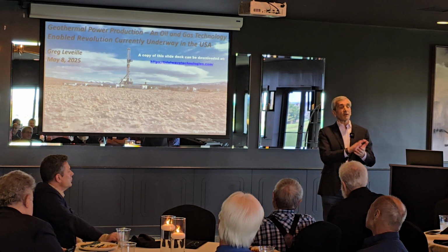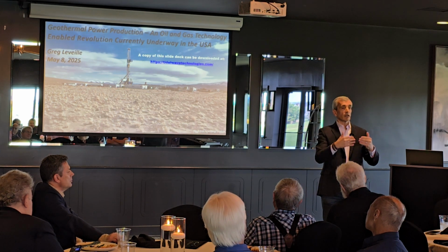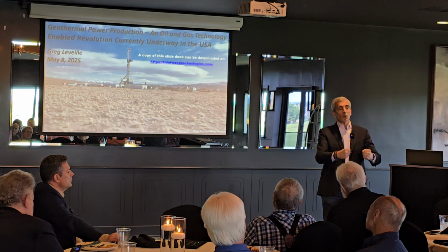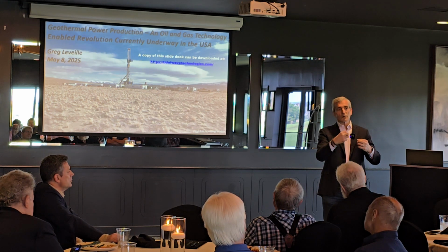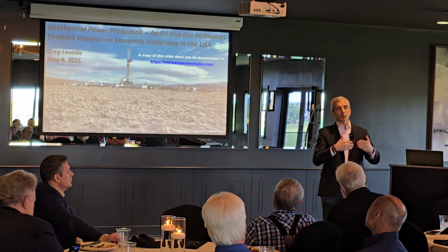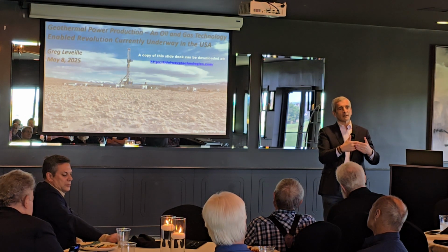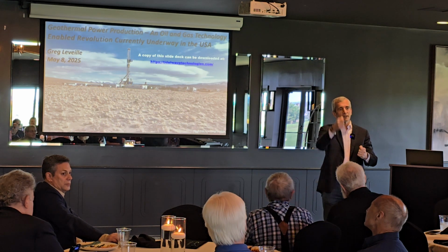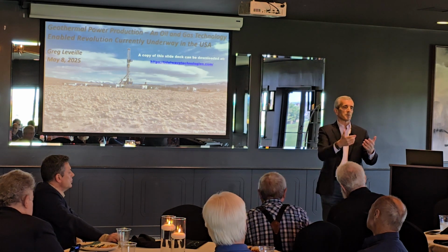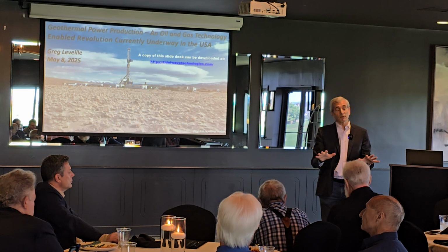Yeah. There's a company called Sage Geosystems that is looking to do just that. They're going to be hydraulically fracturing horizontal wells and pumping water into them, using a combined sort of geothermal and pressure storage. You dilate the fractures when you pump the water in, and it heats up while it's sitting in there. Then when you need it, it comes out, and you use both the pressure and the temperature to generate electricity. So you have those types of options.